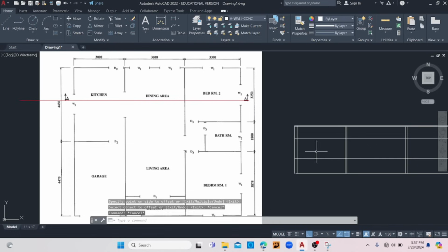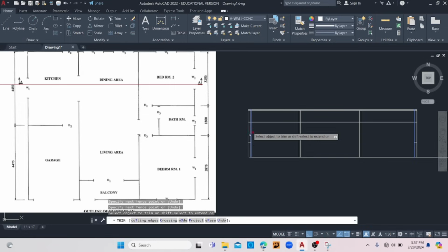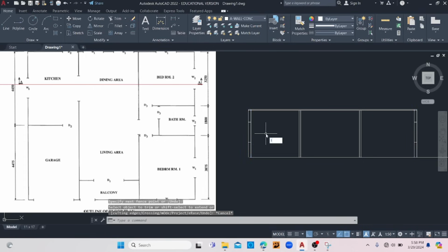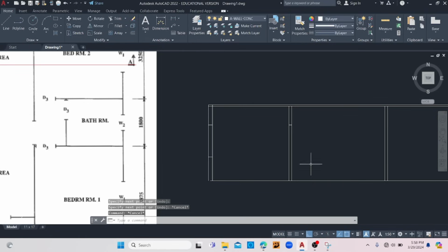like this. And I'm going to clean up my drawing by trimming away, and I'm selecting my cutting plane here, trimming away this portion in the middle here, leaving my big windows there. And then I'm going to show my opening right here from that kitchen to the dining, I think. So I'm going to trim out everything here, and I'm going to redraw this one here using dynamic tracking. Alright, so this is my opening.